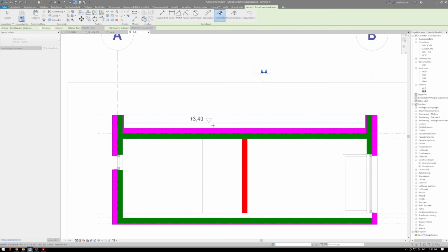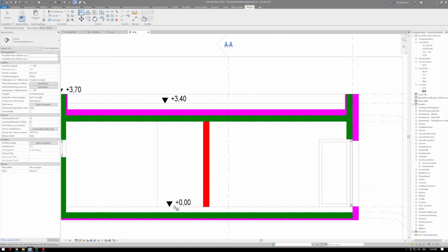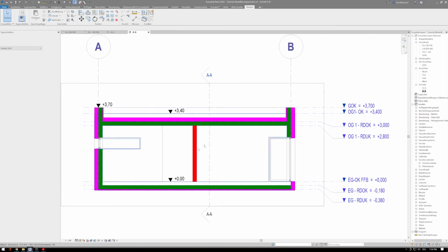It gives me the option to place it underneath or up. I place it upwards, and left or right I pick that the dimension is on the right side. So I move my mouse to the left side. Doing the same thing here and here as well. Perfect. I go AL for align. So I pick the middle point of this triangle and I pick this one as well. So they are aligned together.